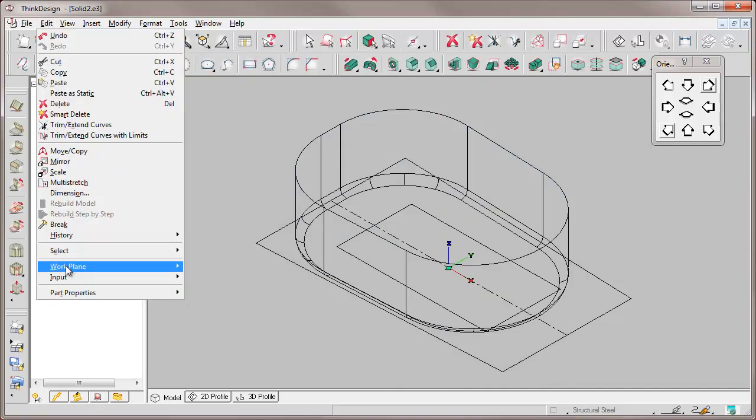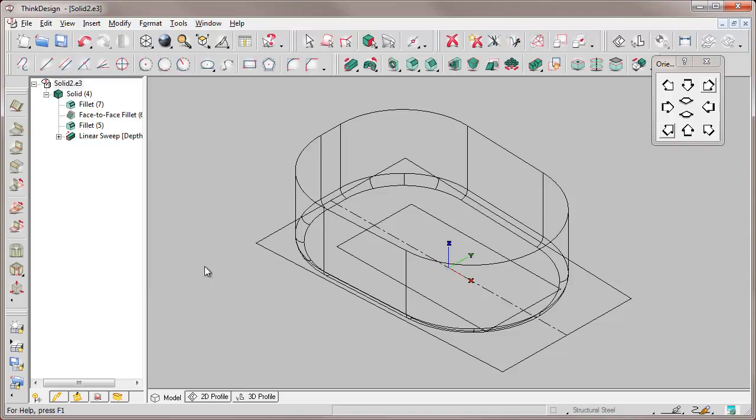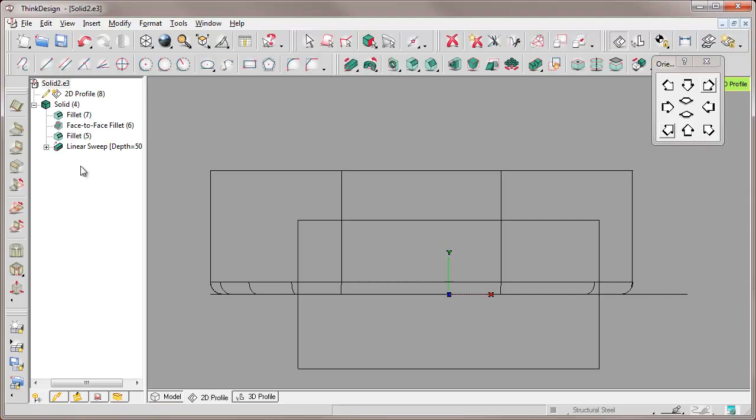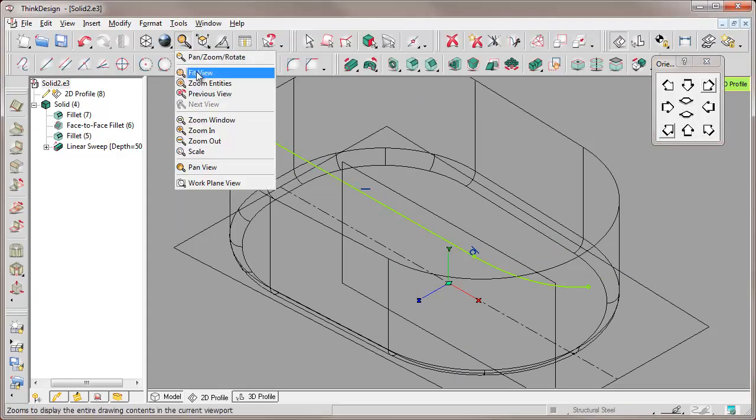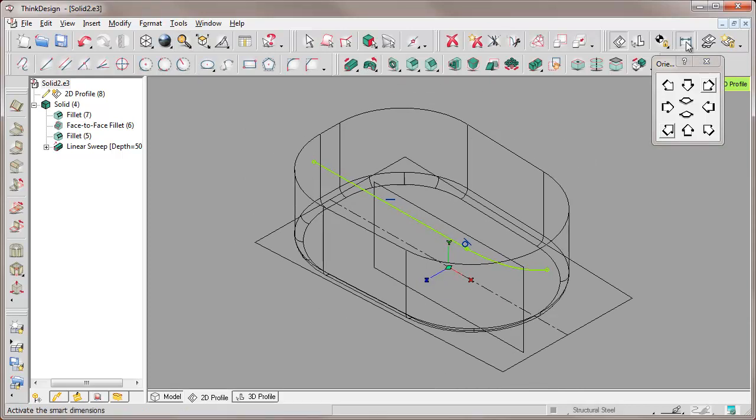Let's change the position of the workplane. We select the circular arrow of the x-axis, and with a double click we rotate the workplane axis of 90 degrees around the x-axis. In fact, we want to have a different x-y plane to create in the profile environment another shape. Using the polyline command, we can start drawing a line and switch to tangent arc, so a tangent constraint between the two entities is automatically added.